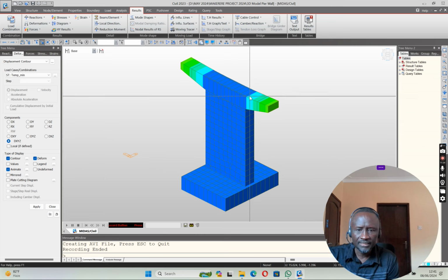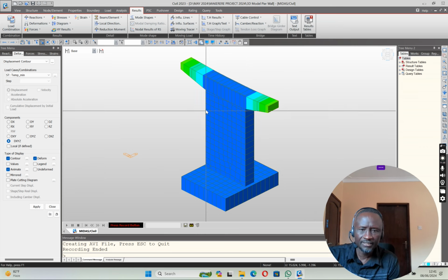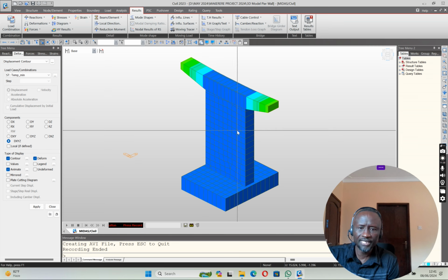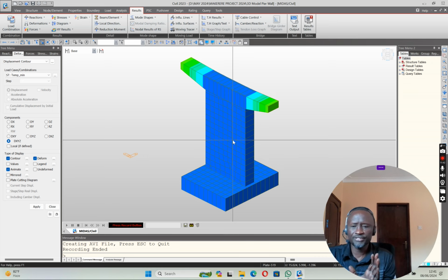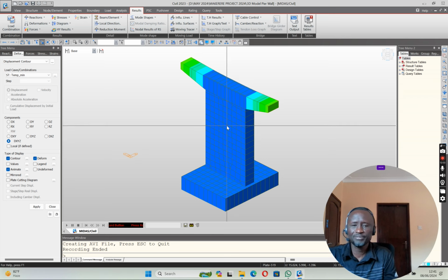If you tilt it, this face here, all that will be experiencing water at an angle, and you have increased the surface of contact with water, and that will definitely cause problems. At the same time, you are having uplift, the bridge is being distorted, the bearings are moving, the whole thing becomes violent, and all limits will be exceeded. Boundary conditions will never be respected at that moment, so you have to be careful.